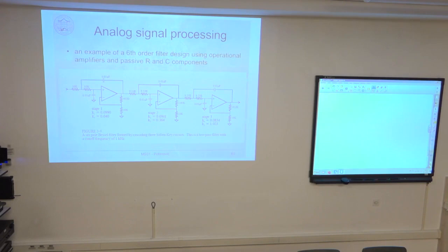It works nice on the paper, it works nice maybe in simulation, but as soon as you implement it on your PCB, something is wrong, something is completely different. Because you have not implemented the real model of these passive components that has all of these parts, resistance, inductance, and capacitance, irrespective of the type of the component.